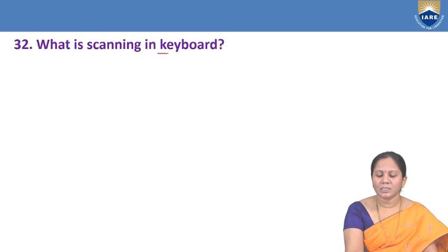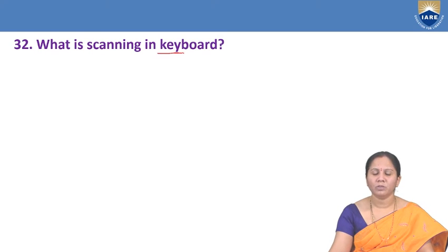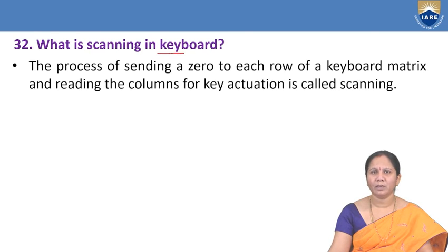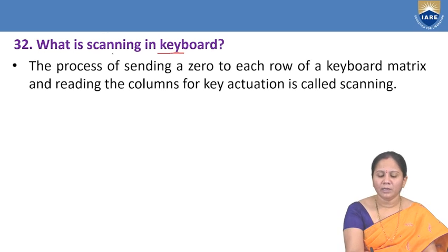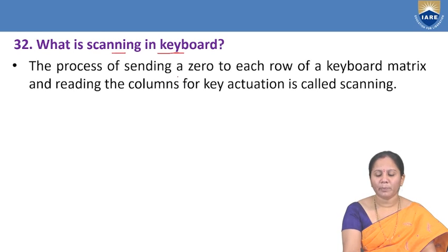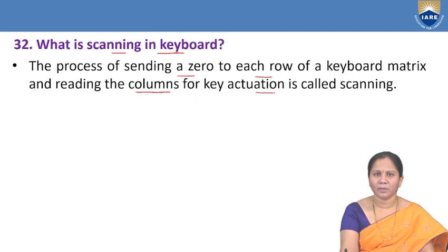Next, what is scanning in a keyboard? What is meant by scanning? This question also relates to the keyboard display controller. Scanning means the process of sending a 0 to each row of a keyboard matrix and then reading the column for key actuation. Totally, it is called scanning.